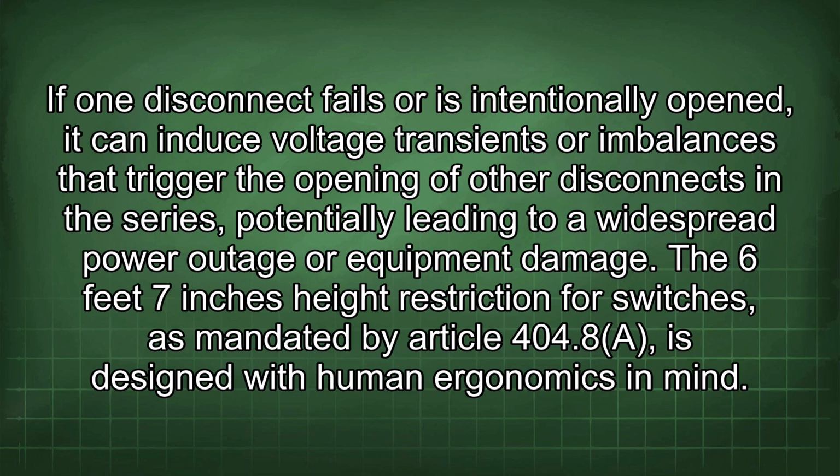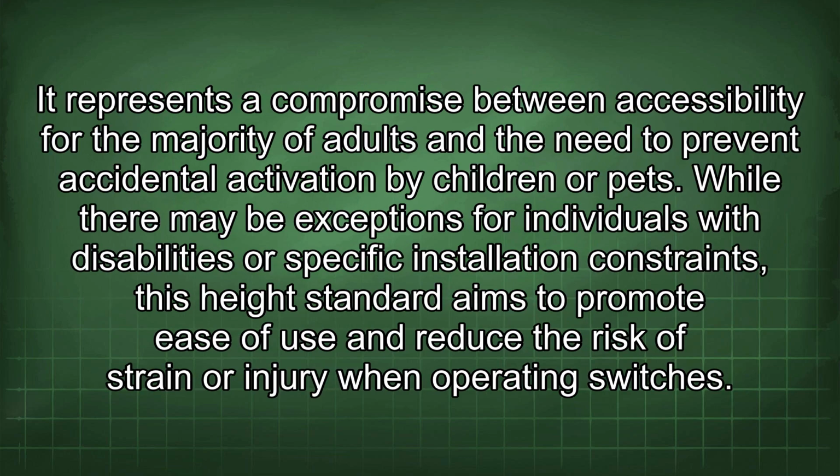The 6 feet 7 inches height restriction for switches, as mandated by Article 404.8a, is designed with human ergonomics in mind. It represents a compromise between accessibility for the majority of adults and the need to prevent accidental activation by children or pets. While there may be exceptions for individuals with disabilities or specific installation constraints, this height standard aims to promote ease of use and reduce the risk of strain or injury when operating switches.